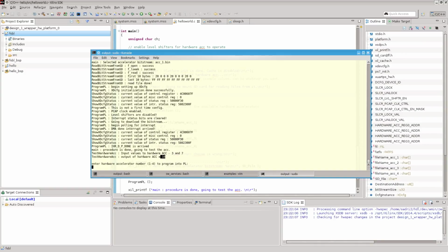There are several important questions here. The first one is how fast we can reconfigure the PL. In fact, this speed can become very important, because you are running an application, you are the ARM host, you are running an application, and then you reach a point in your application where you need a specific hardware accelerator, and you want to program your PL with that specific hardware accelerator as fast as possible.